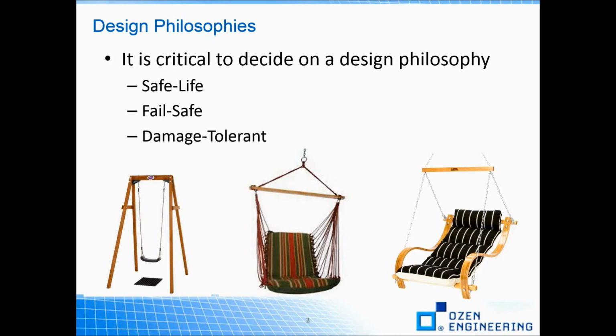One important thing is that before doing any fatigue or fracture mechanics calculation, it is a must to decide on a design philosophy. Will the component at hand be regularly inspected and taken out of service when cracks are found, like in the aerospace industry, or is it to be taken out of service before there is even any possibility of cracks forming, like in mission critical designs? Answering such questions will guide the analyst to decide on a design philosophy.